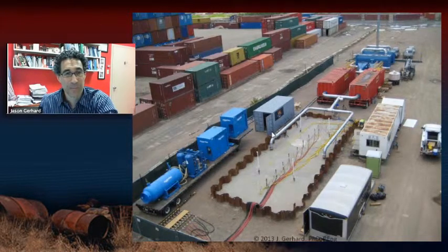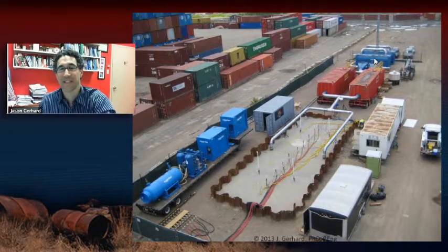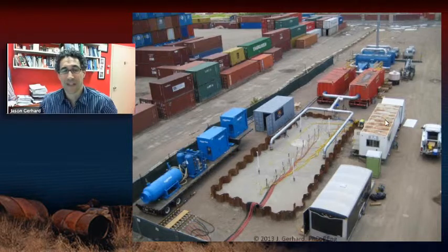And then we have a cap on top with pipes underneath that basically collect all the gases through here. Here we're measuring the integrated CO and CO2 and the VOCs of all of the collected gases, so we know everything that's coming out. These are water knockout tanks. We were worried about having a lot of water vapor. We hardly even used them. It basically didn't have a lot of water vapor. And here is the activated carbon. So everything went through activated carbon. Oh, there's actually also a cooling tank, because you have to have cool gases go into activated carbon. You can't have hot gas. So it cooled the air, and then it went through activated carbon, and then it was released through a stack. And we had a big monitoring truck here that was actively monitoring for absolutely everything, temperatures and gas concentrations.